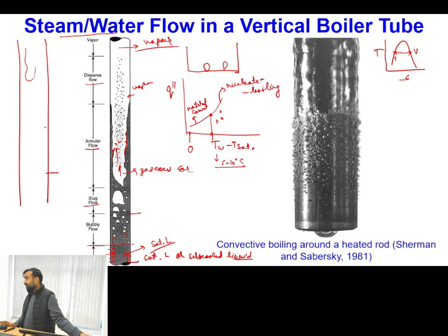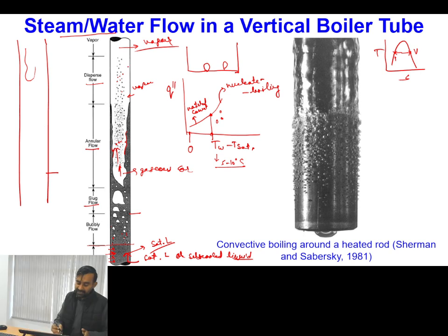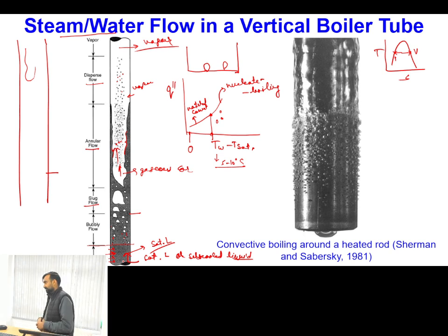But if you are using a pipeline where the flow is not adiabatic, and phase change is also taking place, what will happen? At different portions of the pipeline, the fractions of liquid and vapor will be different, and this leads to differences in local velocity.